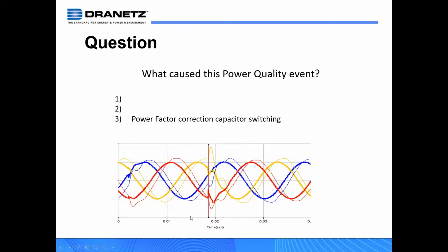Now, different systems can be susceptible to this transient. We've had factories shut down where PLCs cannot handle the transient. It gets rippled through and locks up their computers so they don't work right. We've had medical imaging negatively affected by these power factor correction capacitors. So if you see these issues, you can contact your utility or build in mitigation so these transients will not affect you and your power systems.